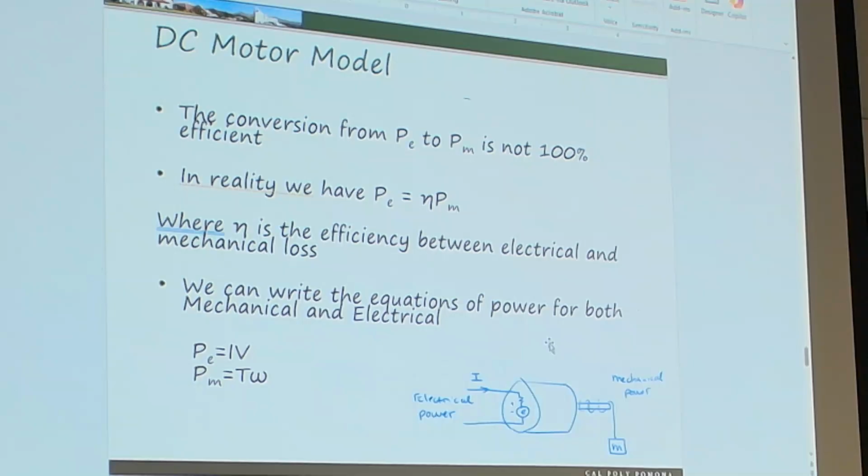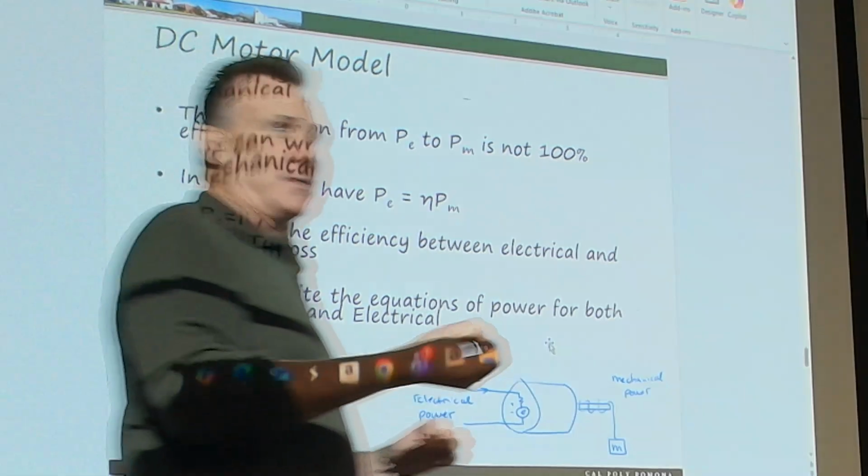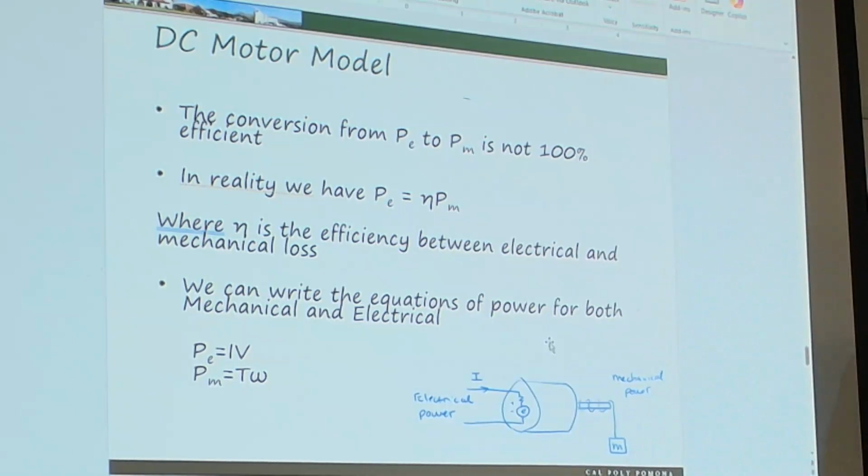Iron, and the big thing is the wire. Now, we said before, if my wire is turning in a field, what is being produced? If I physically turn that motor, it's turning in a B field, what am I generating? A current. So if I have a current and I have a resistance, what do I create? Voltage, right? I've induced a voltage by the very rotation of that motor.